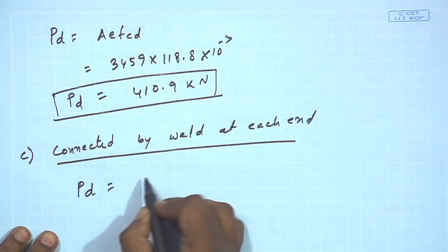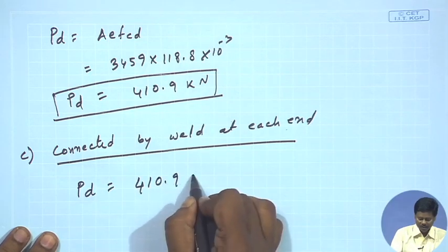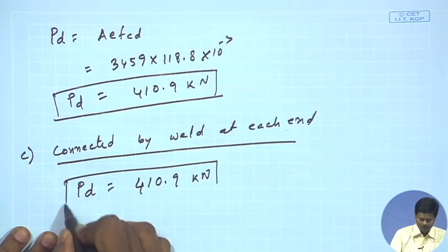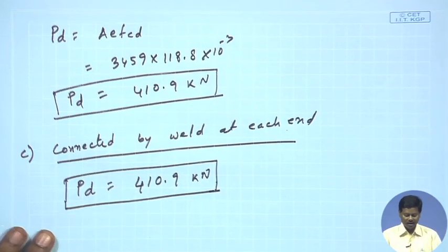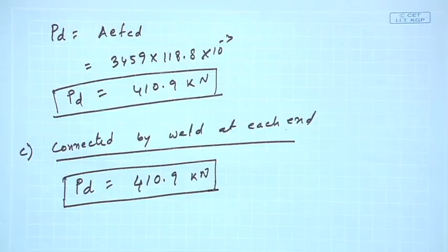So, in case of weld connection we can assume it will be also similar, that it will be fixed at both the ends, and as we have calculated the K1, K2, K3 value considering 2 bolts, for this case also will become same. So, the PD value will become simply same as we have considered earlier. That means, the weld connection and connections made by 2 bolts or more is same, right. Similar behavior we will get when it is in fixity condition.